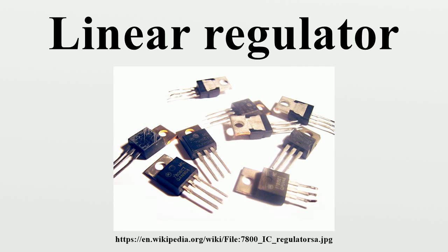Single IC dual tracking adjustable regulators are available for applications such as op-amp circuits needing matched positive and negative DC supplies. Some have selectable current limiting as well. Some regulators require a minimum load protection. Linear IC voltage regulators may include a variety of protection methods. Current limiting such as constant current limiting or foldback. Thermal shutdown. Safe operating area protection. Sometimes external protection is used, such as crowbar protection, using a linear regulator.